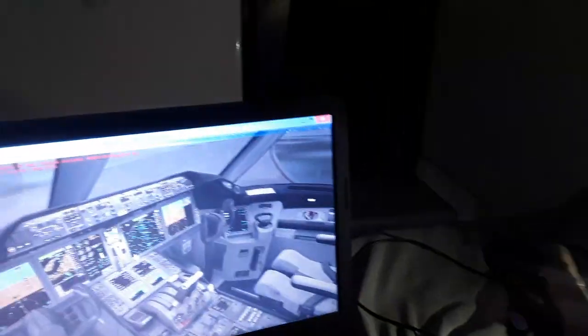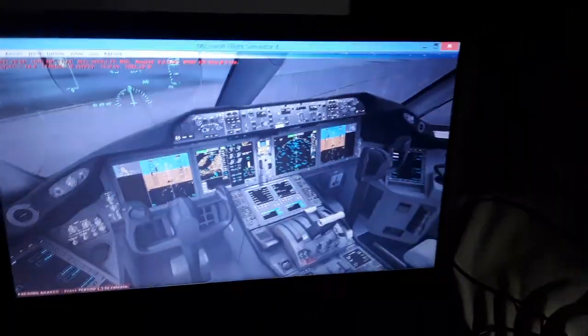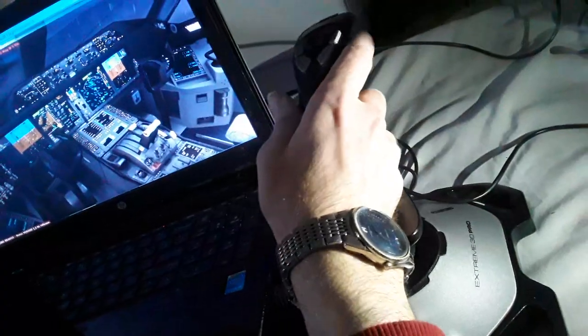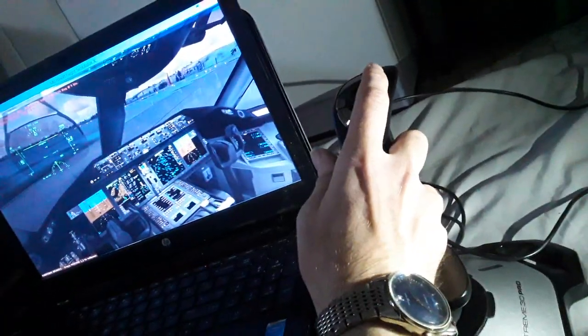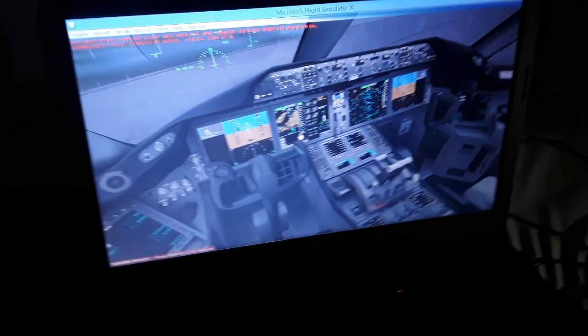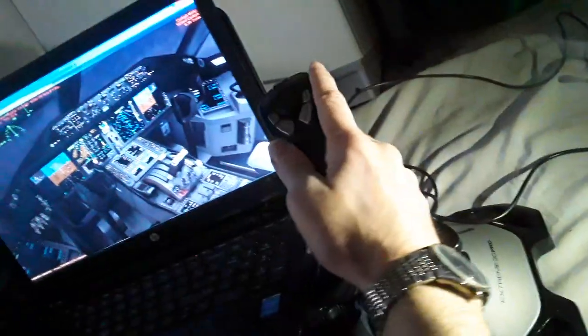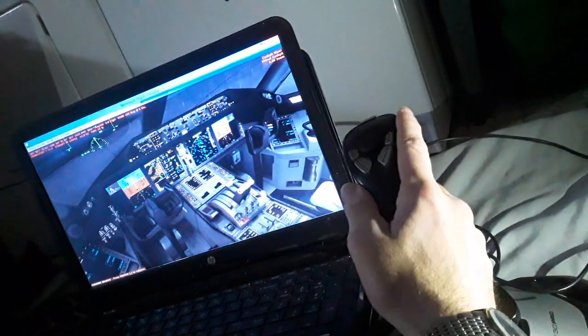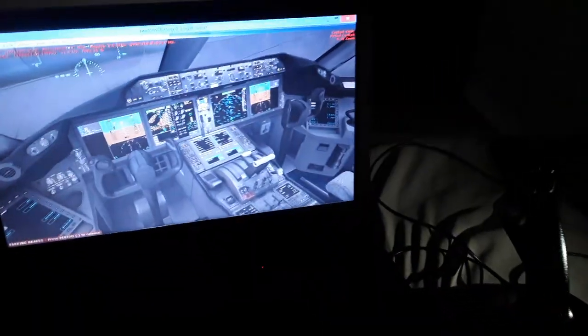So it decreases from 76 degrees of deflection left and right side to about 7 degrees, about 45 knots, until you reach 70 knots in takeoff. Then you have only the rudder, the vertical tail rudder over here, for making left and right directional control. So the aerodynamic effectiveness of the rudder pedals is at about 45 knots. Also you have the toe brakes system in the rudder pedals, so you have a couple more controls.